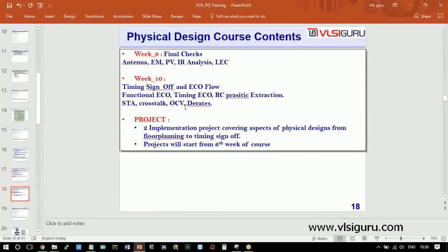Then your generic netlist, your first-level mapped netlist in Design Compiler, then your floorplan netlist, placement netlist, CTS netlist, routing netlist, everything will be different netlists at different stages. This netlist has to be compared against the golden RTL. If it matches logically, then whatever function is there in the RTL will be the same function after all your work. Then you can say thumbs up, yes, my design is equivalent, it can work. Otherwise, there's something wrong, and you have to go and debug what it is.